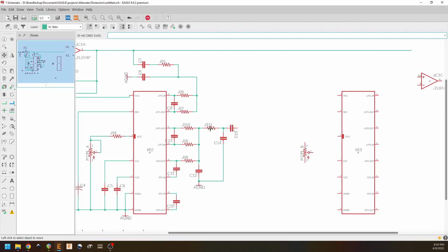multi-feedback filter so that we make sure we don't have too much high frequency roll off. Because if we low pass filter here and then we low pass filter on the input, we might be introducing too much high frequency roll off, so that we end up getting a really weird reduction in high frequencies going from left to right. And if we keep that up, we'll continue to get that degradation as it goes back and forth. And a ping pong delay is meant to be very crisp. So the actual values, we'll play with those once we get on the breadboard.